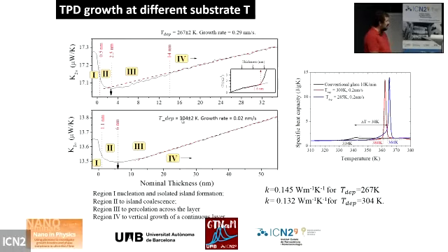And the thermal conductivity extracted from the slope was around 0.14 and 0.13. And I would say that here the uncertainty is in the third digit. Now, this is a very low thermal conductivity material. This is for a 100 nanometers thick material, if I remember well. And even so, we are able to determine the thermal conductivity of the material with these 3 digits.